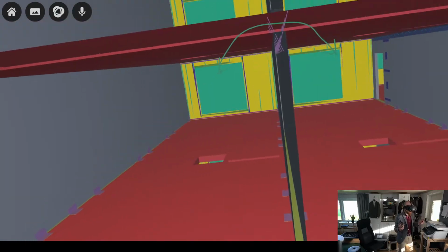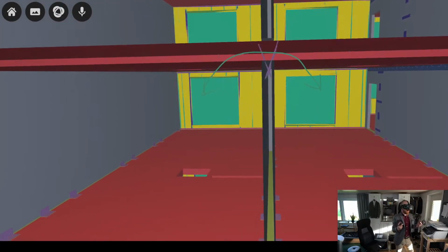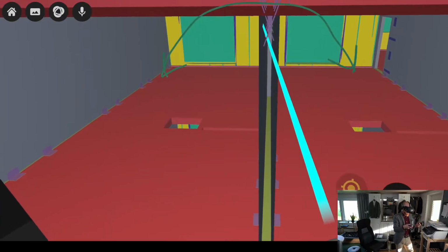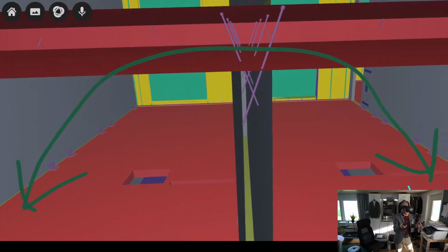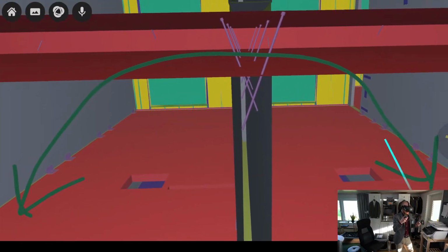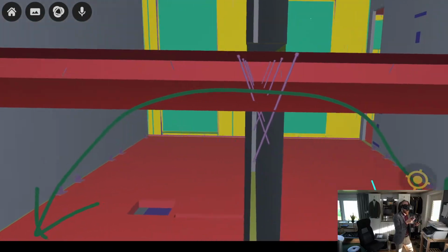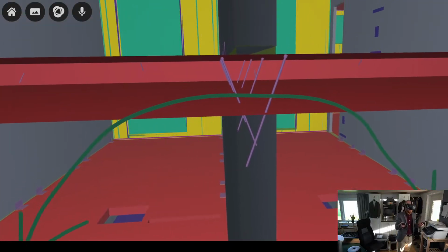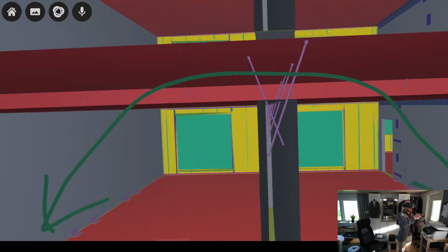The takeaway from this video, I think, should be, if you're working with CLT and designing a building, be very careful about this situation. You do not want to have continuous CLT elements between two dwellings because they are very sensitive to flanking transmission.